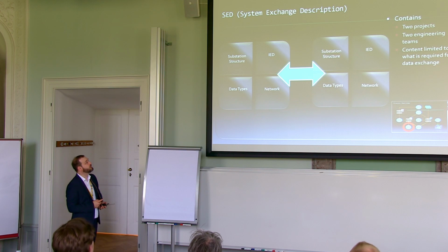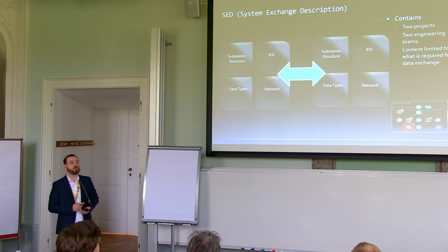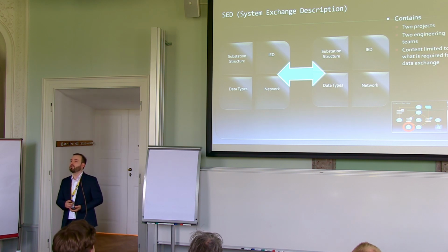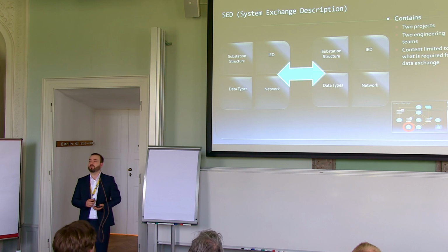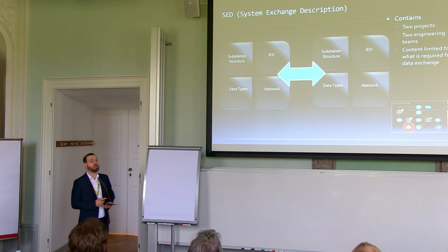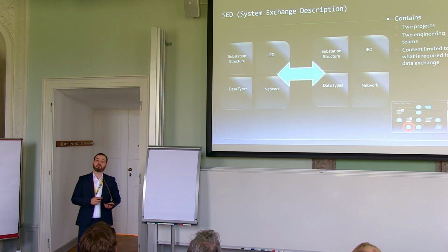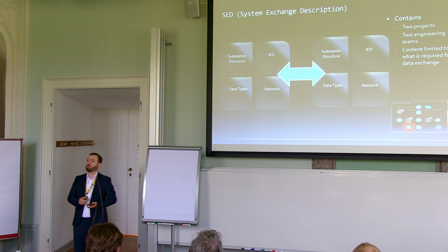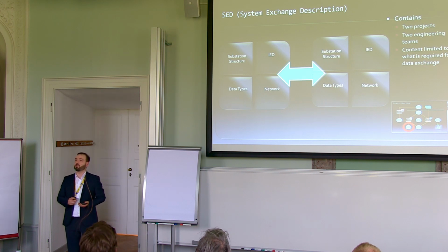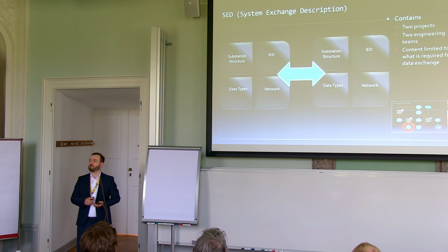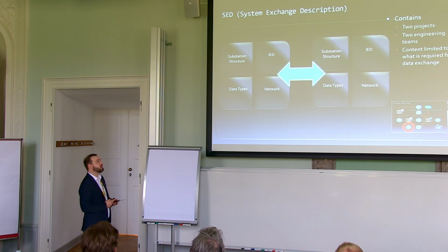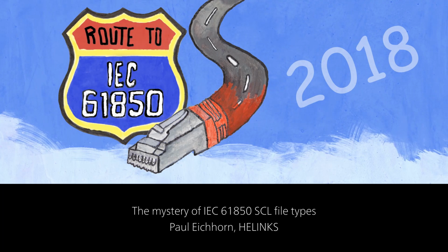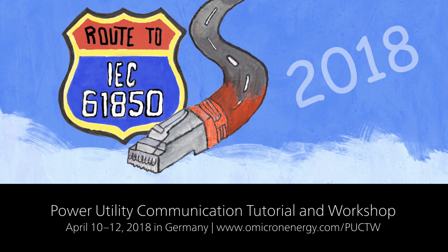And in addition, the IEDs present there may have their engineering rights restricted. So in the IED description, there is a data field for engineering rights. And when you export an SED in your one project, you will set the engineering rights to restricted on the IEDs that you own. You give it to the other vendor or to the other team, or maybe you just hop over to a different computer or a different project and import it yourself. And in theory, the other tool that imports this file will then prevent you from changing any of the IEDs that you don't have the rights to.